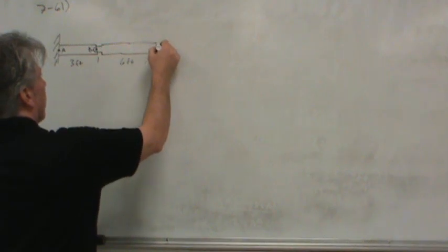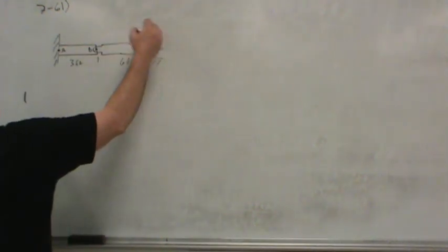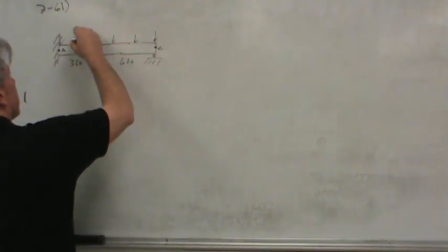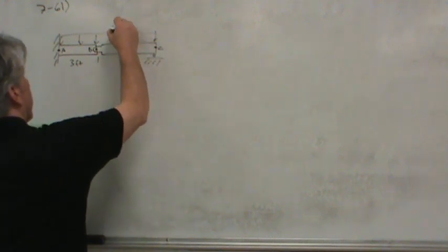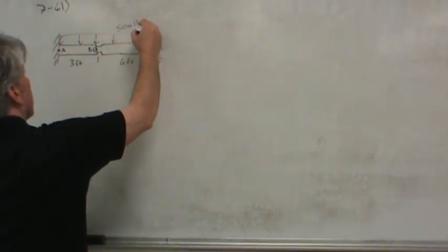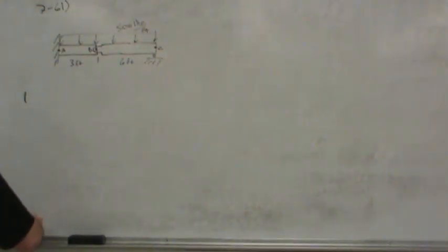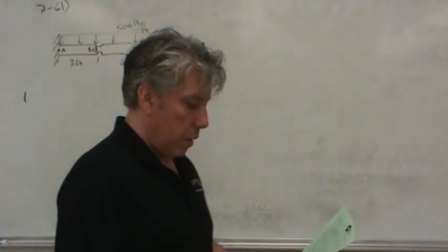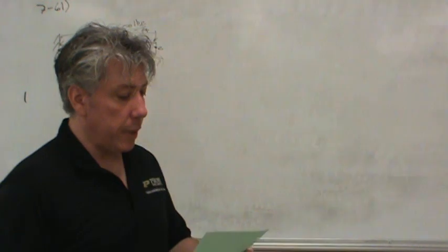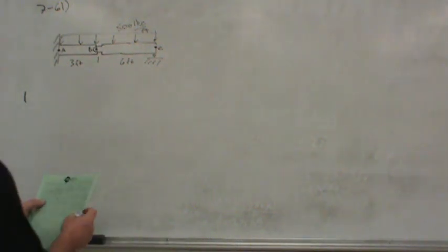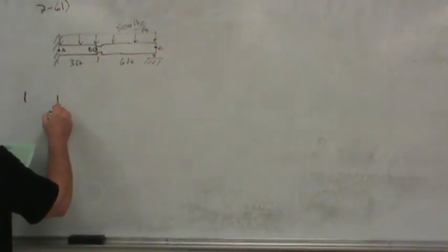Out here at point C, there's a roller to support the remainder of the beam, and then there is a distributed load along the entire length of the beam, magnitude 500 pounds per foot. So the question becomes, what do the shear and moment diagrams look like? And what else is going on with this beam? Because obviously if we're going to size this beam, we want to make sure it doesn't fail due to the internal stresses. So what I'm going to do is break this up into two free body diagrams.